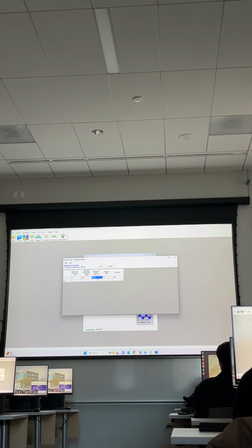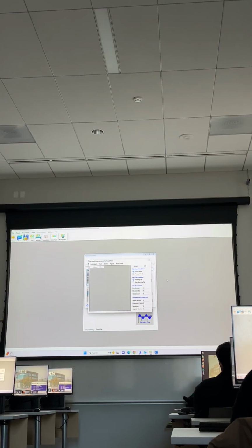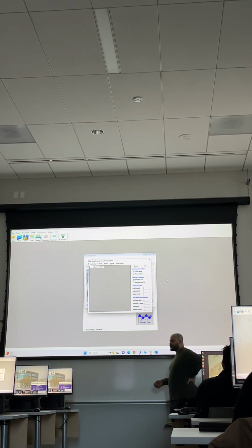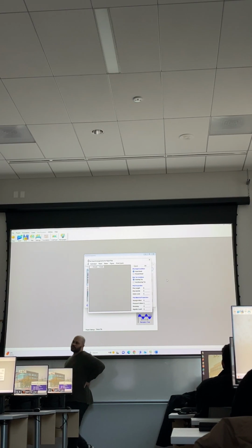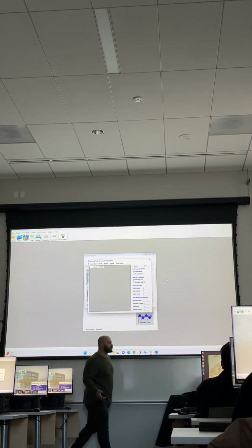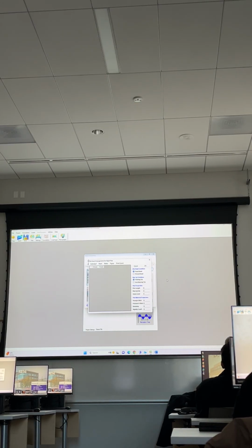different cases to decide which one is the best for your foundation and for your operating speed. Again, I'm not going to change the soil layer, the Poisson's ratio, the damping ratio, all of them is okay. And let's go with the piles. This is mainly the difference between the deep foundation and the shallow foundation, that you have to define the piles.